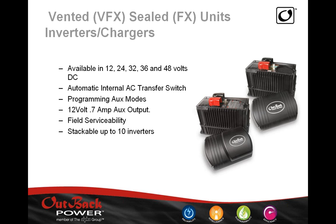These off-grid inverters can be wired to have up to 10 inverters in any system, and we'll get more into that. Basically, we can provide any type of single-phase or three-phase system. Now, in a three-phase, we can only provide a three-phase Y system, not delta, and we provide a 120/208 system.